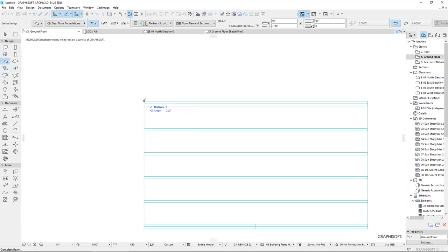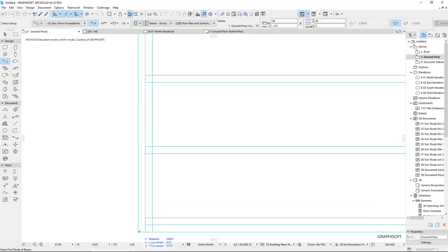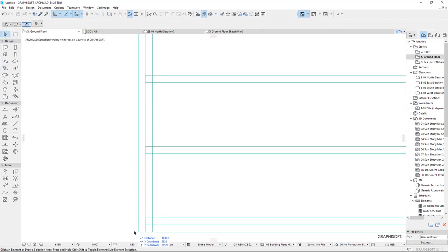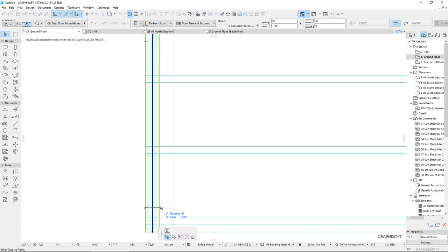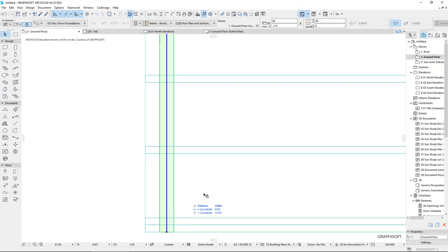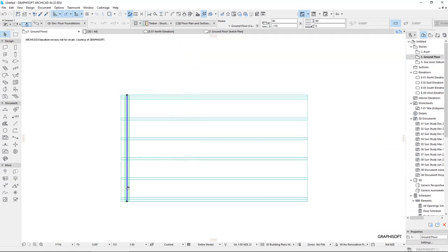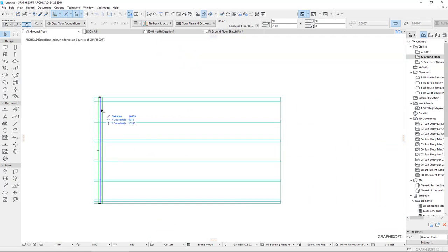So where are we going to put our joist? Well, why don't we start by creating our joist right down that end there. That puts it at the end. We can move it, so back to our arrow tool. Let's move that joist from there to there. This is going to be my bearer. And then we're going to move it by about 100 millimeters. So it's easy enough just to move it one of those. And we can do the same tricks that we did last time. We're going to mirror that to the end so we get another one exactly the same place.